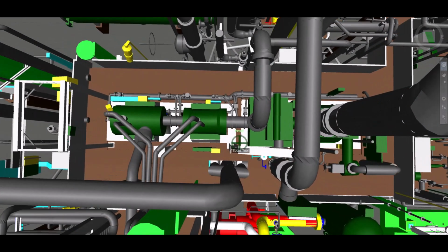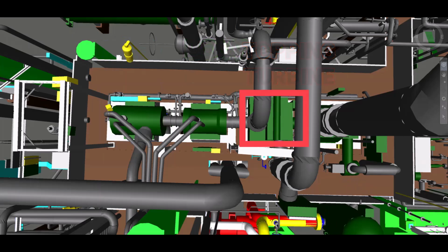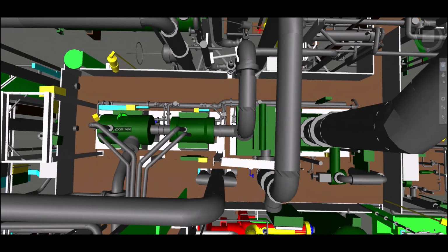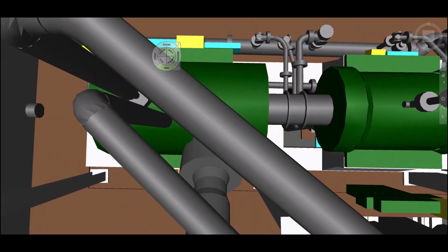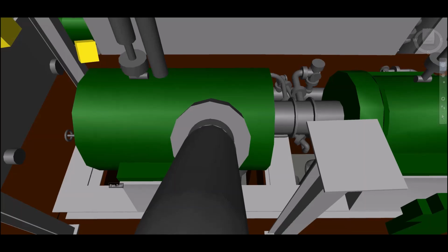With this view, you can easily see the four main sections of the 103J compressor train: the high case, the low case, the topping turbine, and the condensing turbine. This training is going to focus on the seal oil system on the high case, specifically around the oil and syngas mixture after it leaves the compressor seal cavities, which we call sour oil.